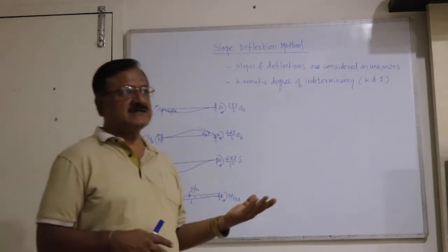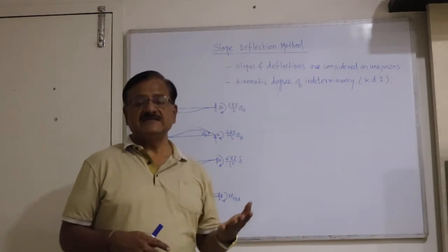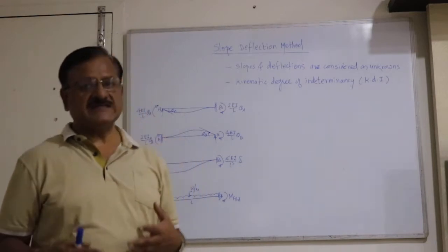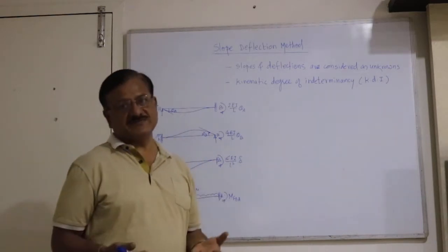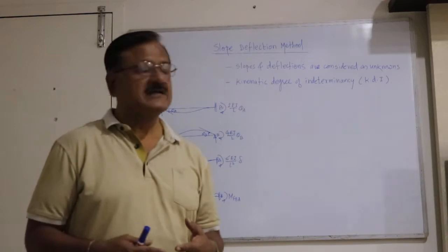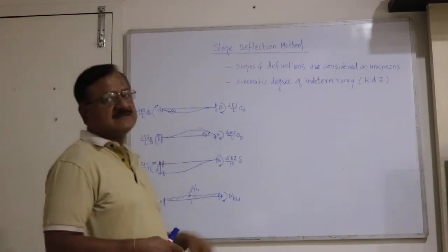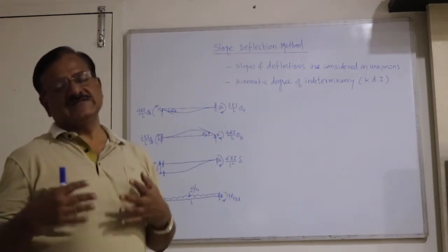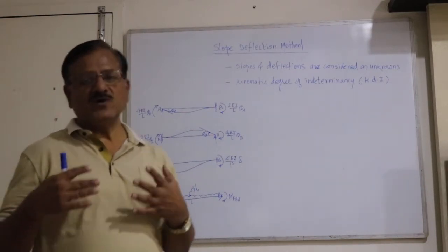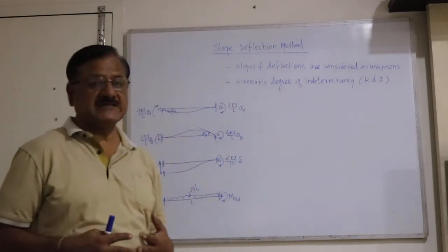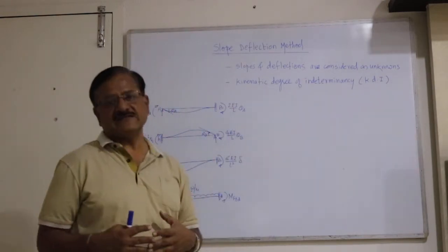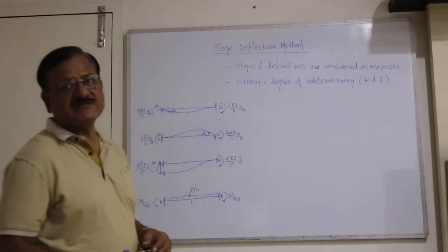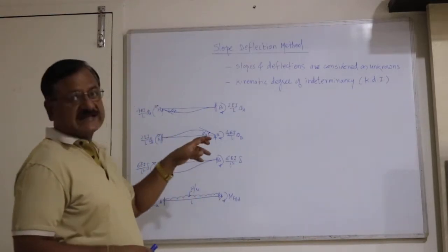In the earlier method, say the strain energy method, we take the forces as unknowns. So that method is categorized as a force method or flexibility method. Here the displacements are considered as unknowns. Later on we will study the displacement type method in more detail, because displacement methods are more suitable for programming purposes. That we will see in matrix methods of structural analysis in the next unit.